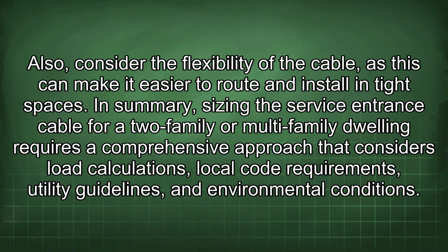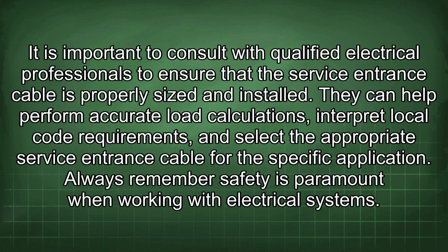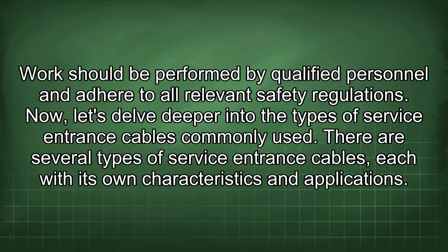In summary, sizing the service entrance cable for a two-family or multi-family dwelling requires a comprehensive approach that considers load calculations, local code requirements, utility guidelines, and environmental conditions. It is important to consult with qualified electrical professionals to ensure that the service entrance cable is properly sized and installed. They can help perform accurate load calculations, interpret local code requirements, and select the appropriate service entrance cable for the specific application. Always remember safety is paramount when working with electrical systems. Work should be performed by qualified personnel and adhere to all relevant safety regulations.